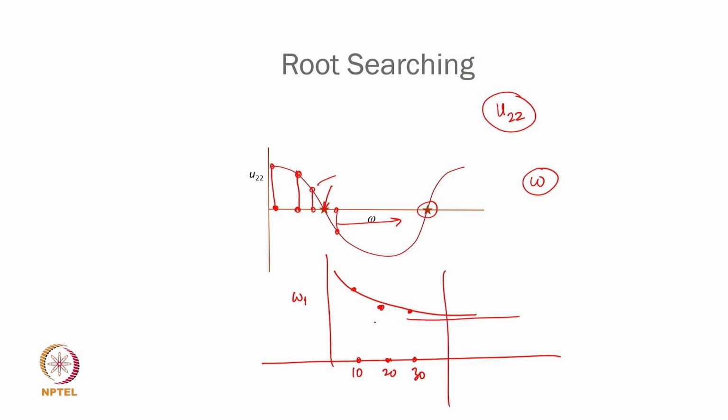So you then decide what is your tolerance value, what error you can tolerate for the first one. Typically people do it for the first 5 eigenvalues, depending again upon what is the rotational speed of your crankshaft, sorry, the shaft of the gearbox. What frequencies are you interested in? The highest of those should not have a large error just because you are discretizing into a smaller number of segments, because the larger the number of segments, the computation increases.